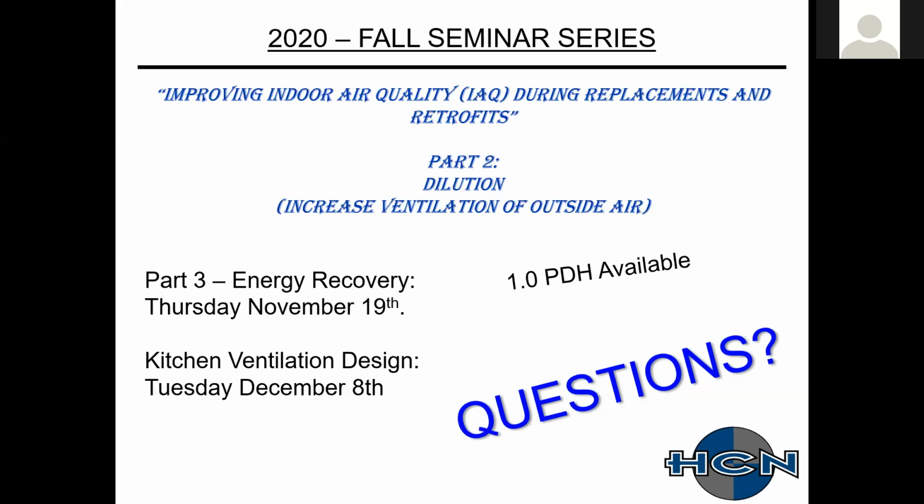The last one is a comment. It would be great if AAON could add humidification as an option. So there are specific sizes in the AAON family that we can add a humidifier. We would be looking at the RZ, which goes from 45 tons up to 240. And we have the RNA horizontal rooftop unit, which we can do an extended discharge. Instead of being a down discharge, it would be an end discharge. And we can extend that and put in a drain pan and a humidifier grid in that particular unit. And that goes from 9 tons up to 30 tons.